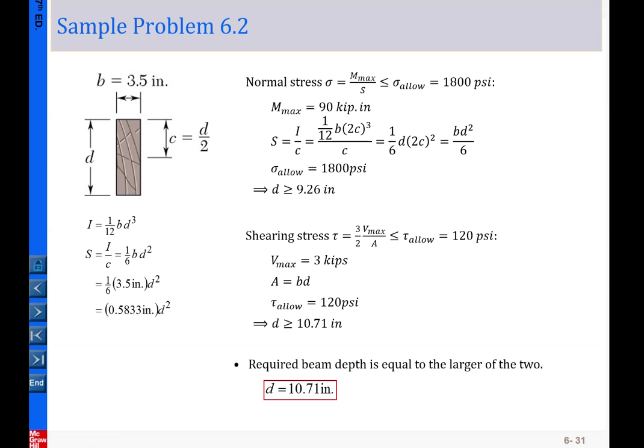So now for our case, first we check against the normal stress criterion. We need to satisfy this one, and we are given this value. So here we simply plug in. From here, we're simply using the stress equal to My over I in terms of magnitude, and that can also be in terms of the S here, which is our textbook solution, but here we can exercise.